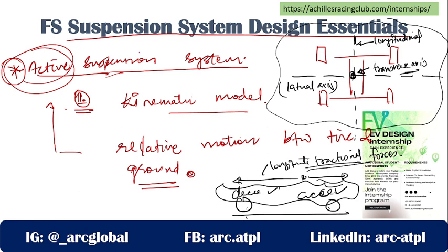If someone is pushing my vehicle, again, this is a longitudinal force. But this time, this force is not acting on the tire center contact patch, but it is acting on the center of gravity position. The aerodynamic forces acting on your vehicle, again, act on the center of gravity of the vehicle, but not on the tire center contact patch. But all these forces are regarded as longitudinal forces.